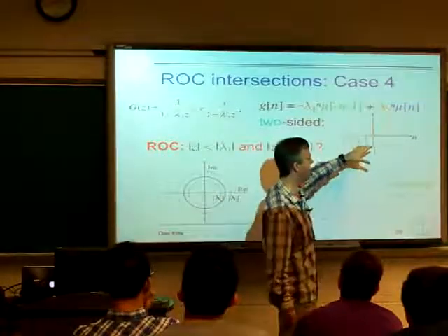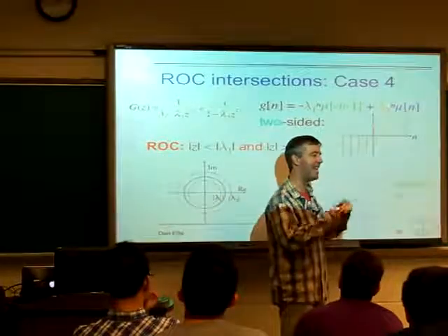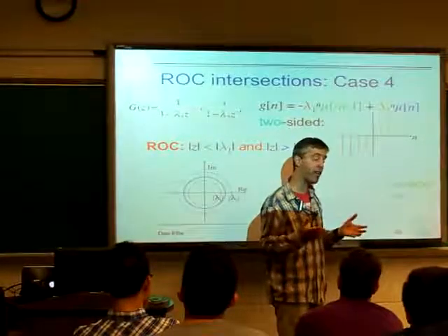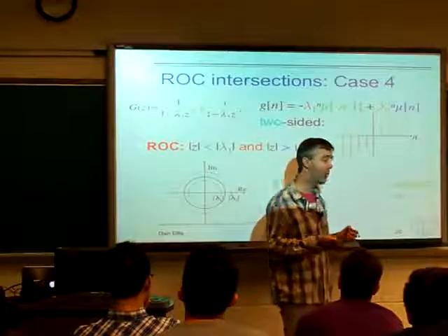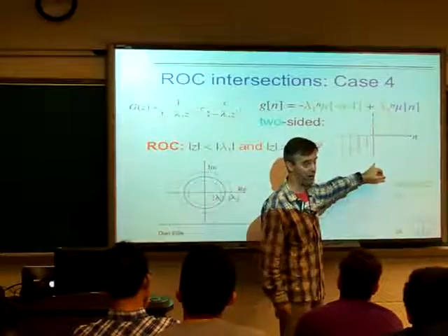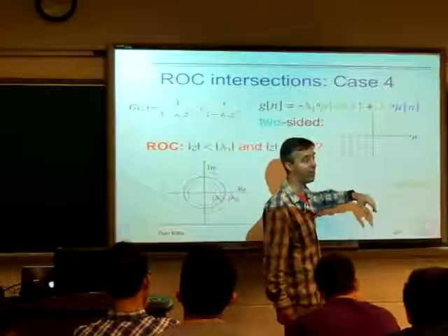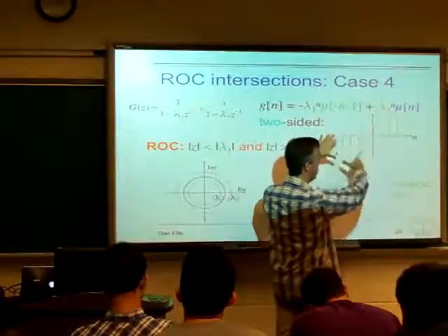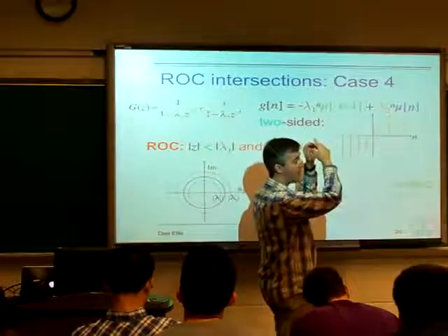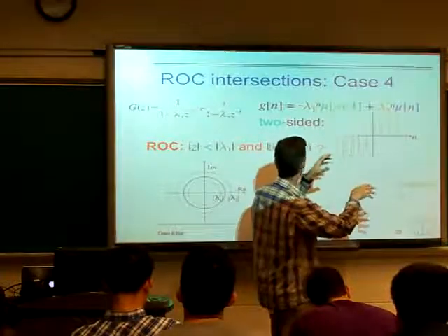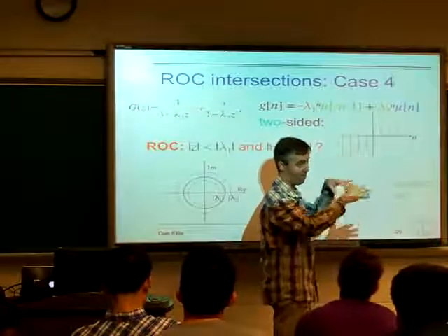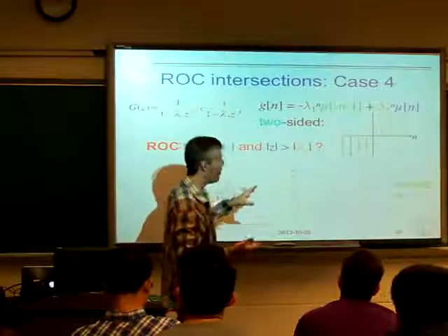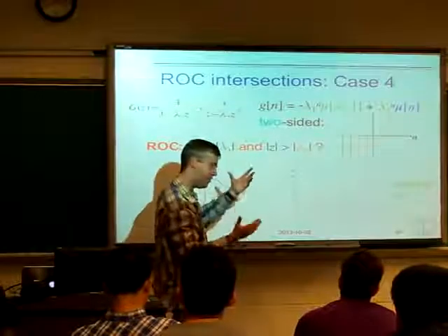And so we said that the Z transform can describe sequences that we are unable to describe with the Fourier transform. But here's a sequence where we're unable to describe it with a Z transform because there's no value of Z for which it converges. So this is exploding in multiple ways. What this says is there's no value of R for which R to the n times g of n is convergent, and so we basically can't handle it with the Z transform. But you see how it kind of emerged out of the way we're thinking about it.